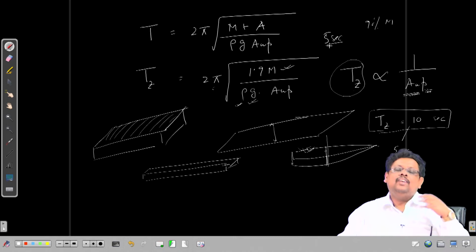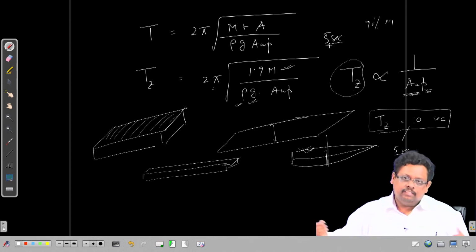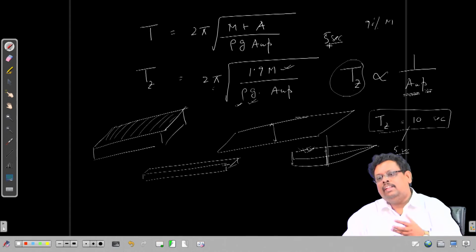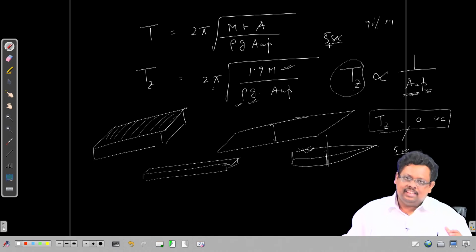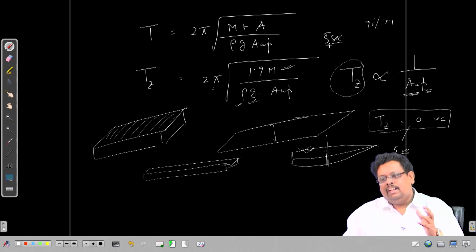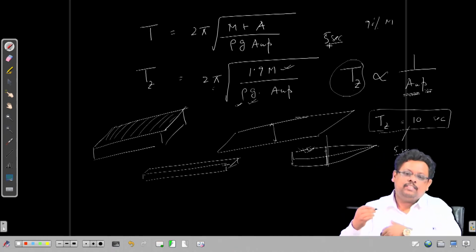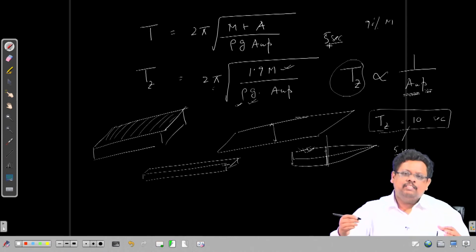Now, see, in one sense, if you are compromising on the comfort of the person, your ship might be more stable. And if you are thinking about the comfort of the passenger, maybe you have to think about the stability, and you have to look out for it. That is why design becomes very interesting in such a situation, because it is so counterintuitive. I am looking for the comfort of the passenger, I am compromising on the stability of the ship. And at other times I try to make the ship very stable by increasing the beam, and then